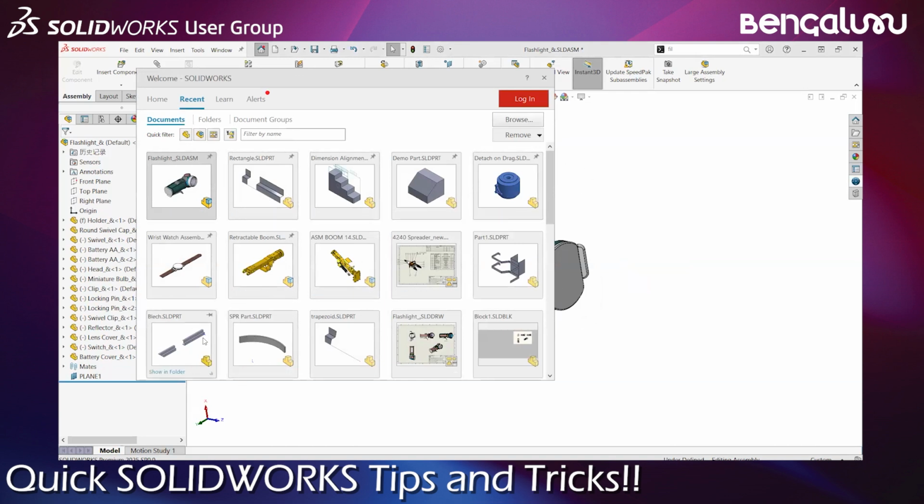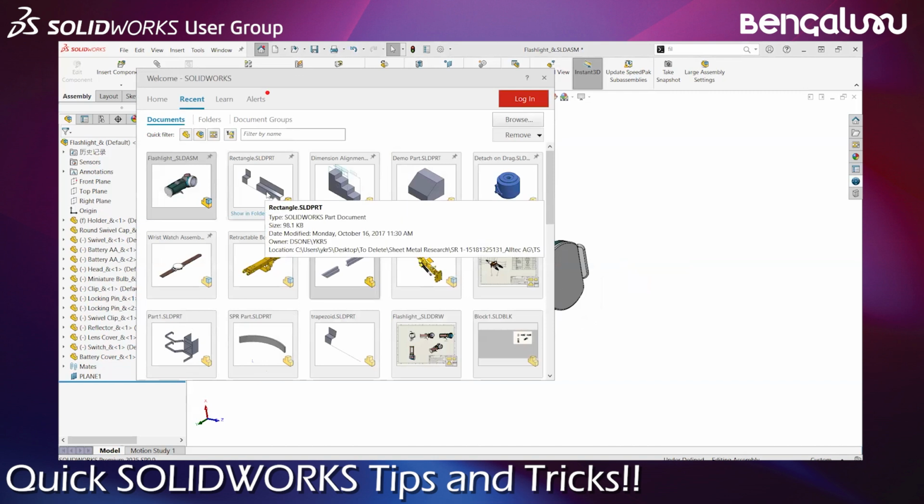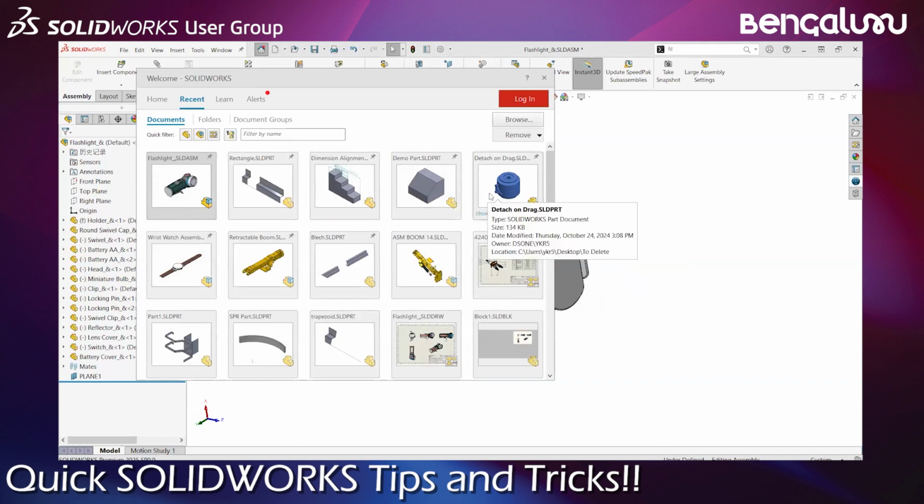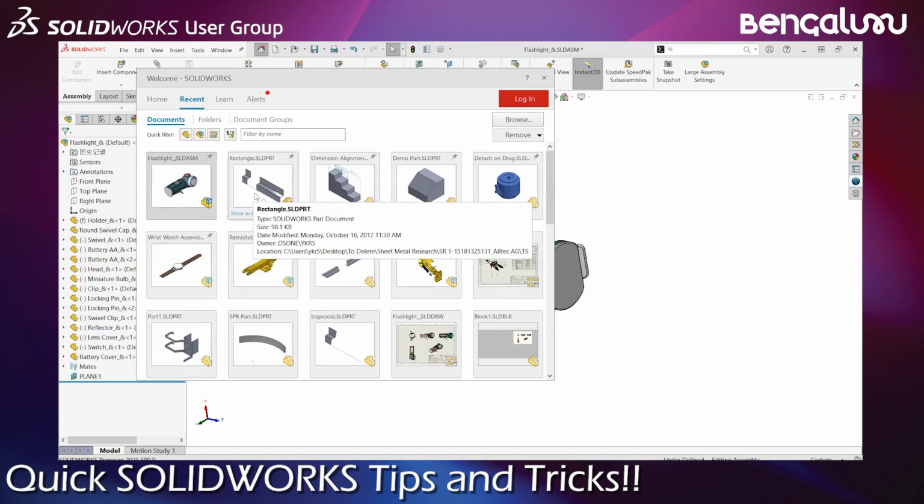You can see that when you hover over any of these documents here, you get this pin command. You can just pin them, and it makes sure that whatever documents you have pinned always stay on top. Irrespective of how many documents you open after these, it will make sure that it's always pinned and available on top for you to quickly open. This is very, very helpful when you're working on major projects and you open hundreds of components, but you still want to quickly access the main assembly each time. So it will be easier for you to quickly pin them.